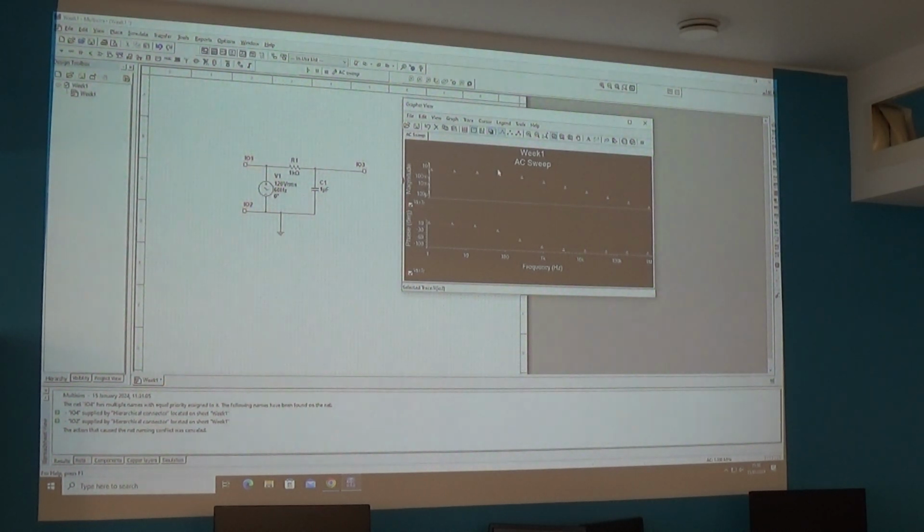So you can see what that circuit is doing is it's letting through the low frequency and it's blocking the high frequency. That's exactly the kind of filter that you have on your telephones. So on your telephones, you've got a deep voice like mine. I don't doubt I go above about 2 kilohertz. But most people, including females, can go up to about 8, 9, possibly even 10 kilohertz. But you don't want to hear anything beyond that, because that's just noise. It's high frequency noise. This is the kind of filter that you would use to remove those high frequency components.